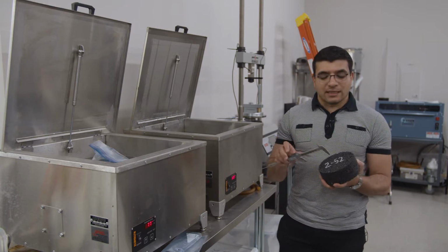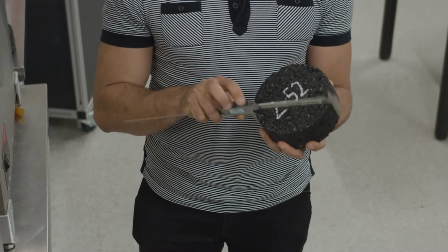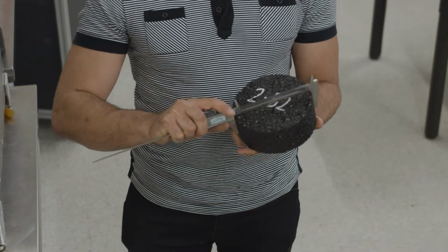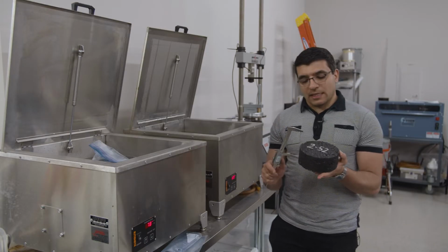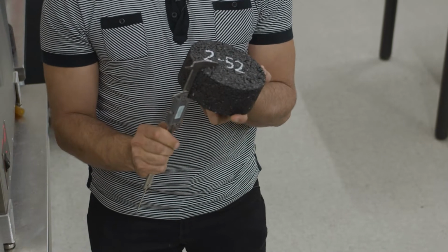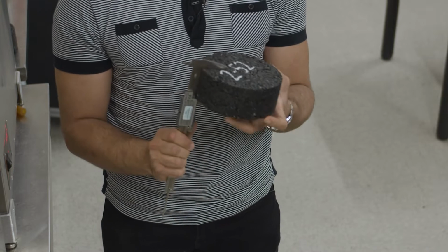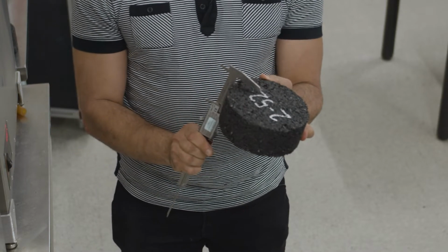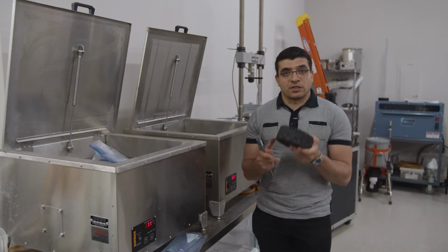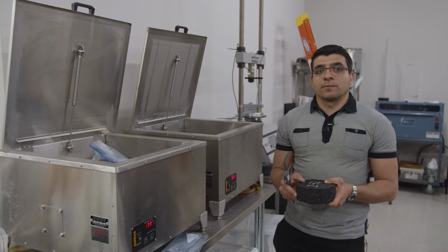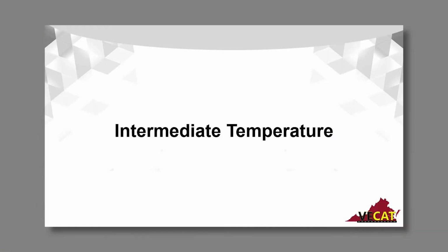We will be determining the diameter at two perpendicular locations, and then we're going to average these two values and have an average diameter value. For the height, we'll be determining the height at four locations, and then we're going to average these four values and have an average height value. The determined diameter and height will be fed into the software prior to conducting any performance tests, and will be used to perform any calculation resultant from these performance tests.